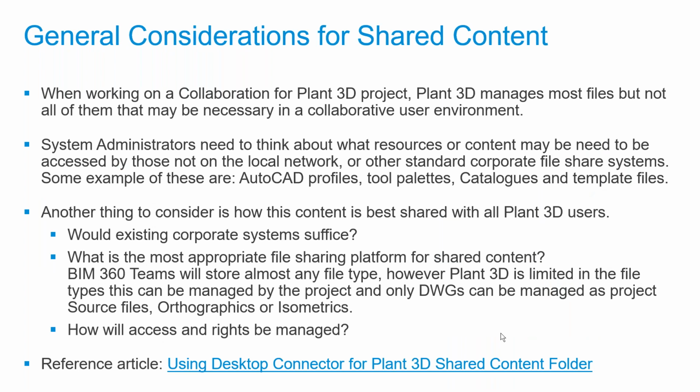General considerations for shared content. Now this is something we've been looking into recently because we get this question a lot. So the actual content folders for Plant are not by default shared to the cloud. For example, the Plant 3D catalogs, when we say content, that's what we're talking about. Shared content is the part catalogs. Those are still in the local C drive.